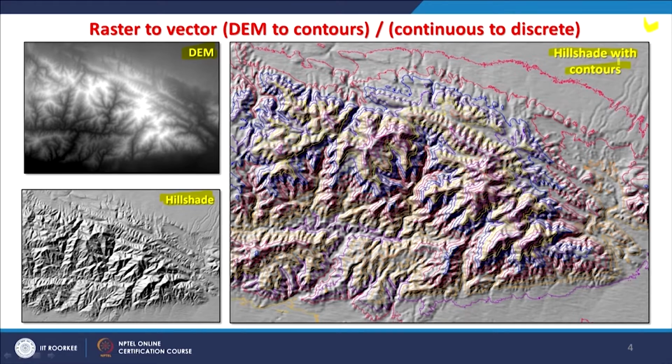So, declaring to the system that I want contour intervals starting from here and with this interval. Whatever interval I decide, whether 1 meter, 10 meter or 20 meter, because remember one important thing here: though spatial resolution might be 30 meter, that is in the horizontal scale, the vertical scale, that is the Z unit, is in meters. So, at most I can derive contours of 1 meter interval, that is the best possible.